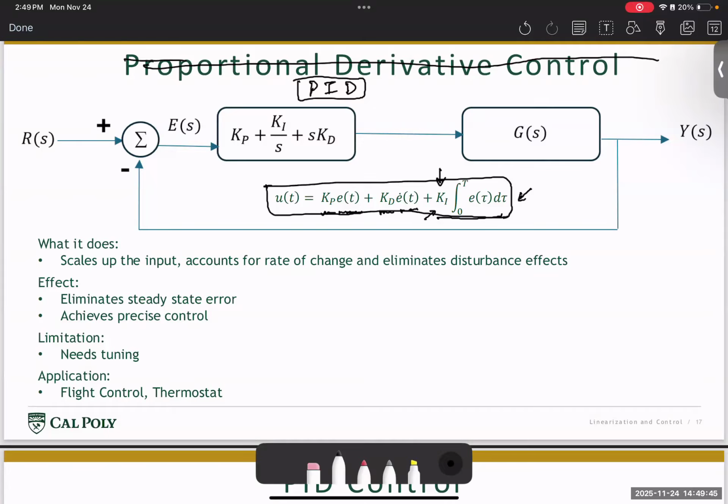All right. But one downside of a PID controller, which we will discuss in the next lecture, is that it needs some amount of tuning. You have to figure out what is a good amount of the Kp, Kd, and the Ki values for the gain you want to set into your system. And this requires some trial and error.